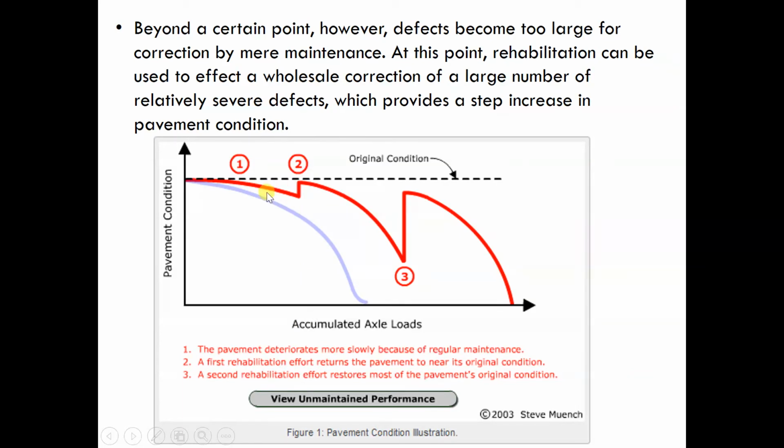So in this phase, like point 1, the pavement, because you've got the potholes, you can seal it, you can patch it. You've got cracks, you can seal them. If there are some road defects, you can correct them straight away. It will slow down the deterioration.